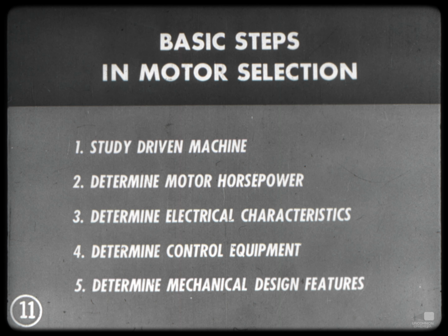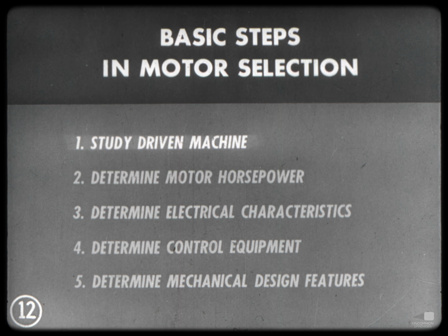Let's take a close look at the 5 basic steps usually followed in motor selection. Study the driven machine, determine the motor horsepower, determine the electrical characteristics, determine the control equipment, and determine the mechanical design features required. It's logical, of course, that the driven machine should be studied first, because this shows what the